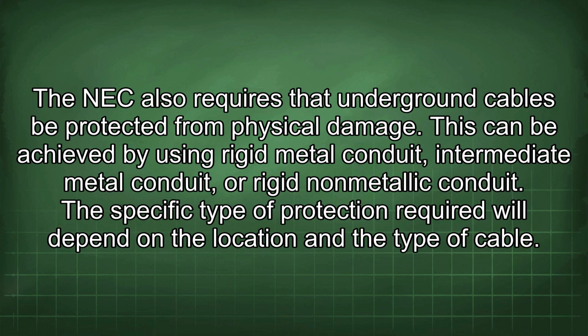The NEC also requires that underground cables be protected from physical damage. This can be achieved by using rigid metal conduit, intermediate metal conduit, or rigid non-metallic conduit. The specific type of protection required will depend on the location and the type of cable.